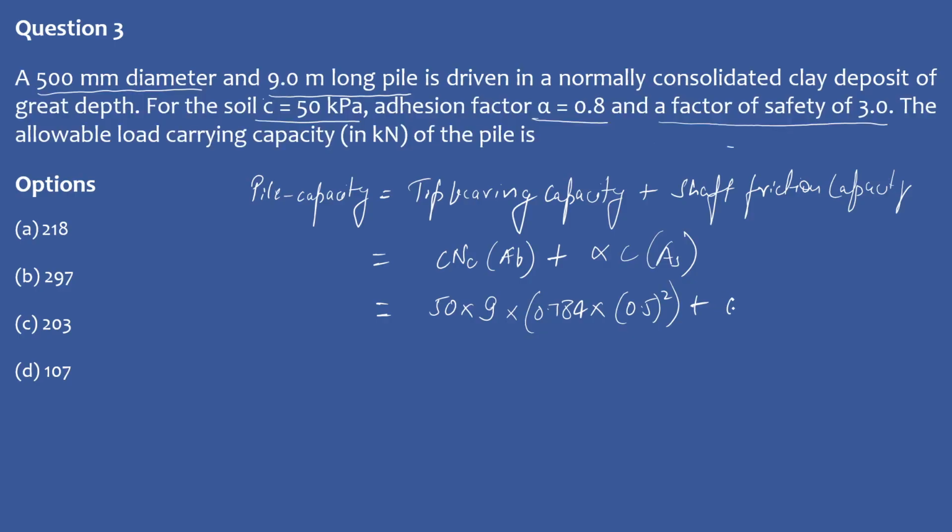Then you have the adhesion factor 0.8, and the cohesion value 50. Surface area is pi d L, so pi into diameter 0.5 and your length is 9.